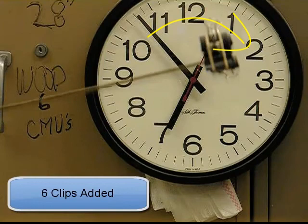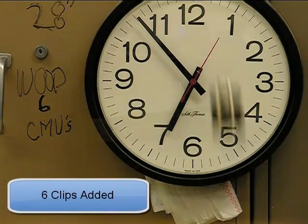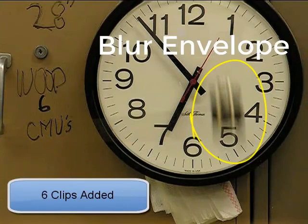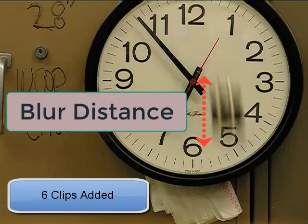If we continue the motion of the cantilever and stop it later on, we can see here it's not very sharp. The image is blurred. This is called the blur envelope. From this you can tell that it's actually moving a lot faster, because remember, each frame is the same amount of time. So here the blur envelope can give us an indication of the speed of the cantilever at that moment in time. Speed is found by taking the blur distance in the frame and dividing it by the frame time, which will give you the speed.